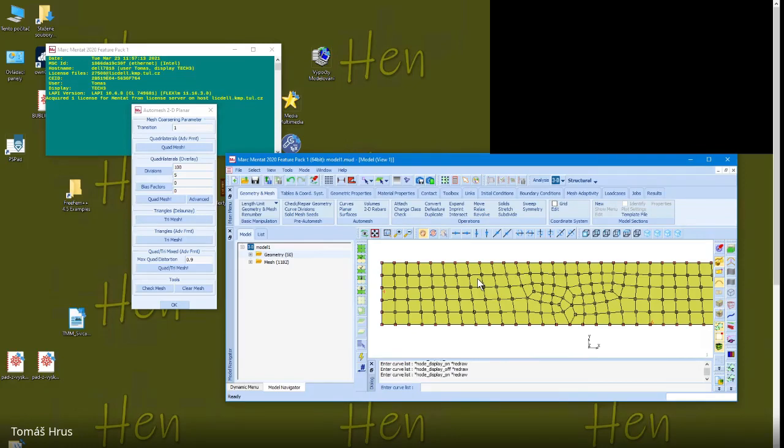That means if we have the mesh, the result is displacement of each of these points. Because we will work in 2 dimensions, each point has 2 components, x and y. If we have, for example, 1,000 nodes, the result is 2,000 numbers: the x and y displacement of the first node, x and y displacement of the second node, and so on.